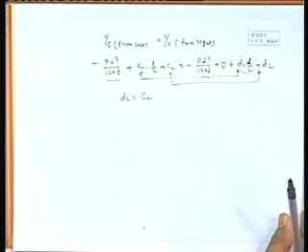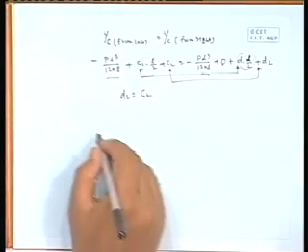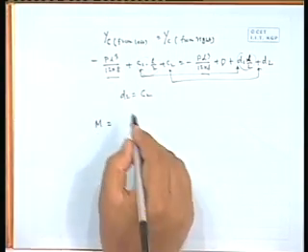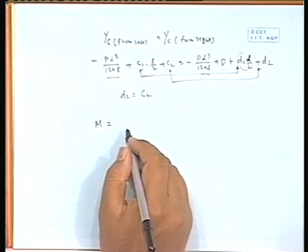Now from there we can think in that manner, we can take the expression of the last span. So the last span will retain all the quantities of the previous one with some additional component, and the constants, whatever we get, will be identical for all of them. Okay. So it can be rewritten in this form. Say this particular beam problem, we can write M in this manner. So for the left span we got M equal to P x by 2.